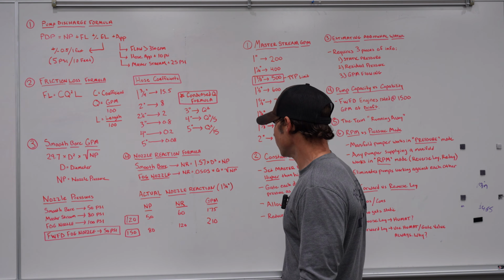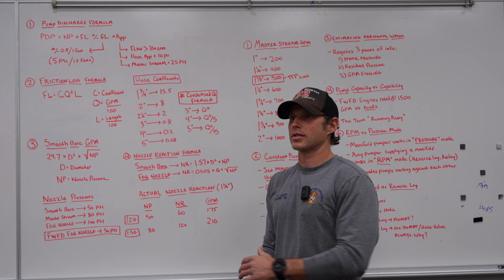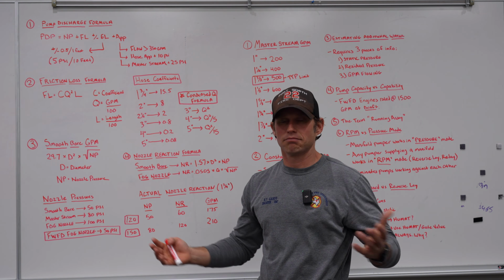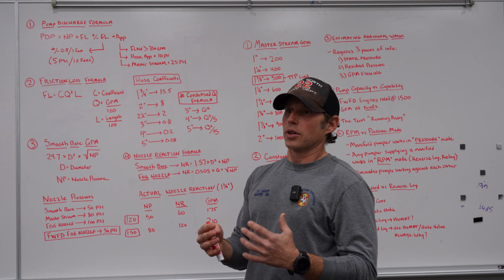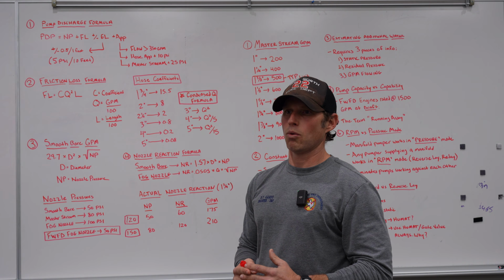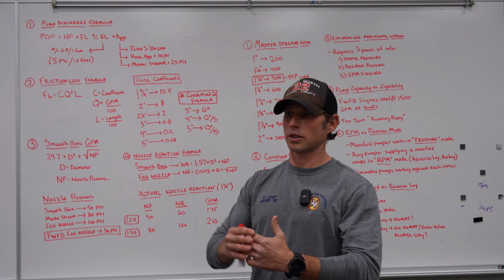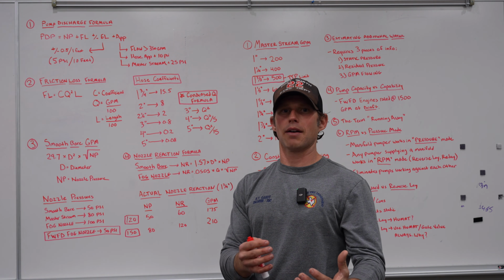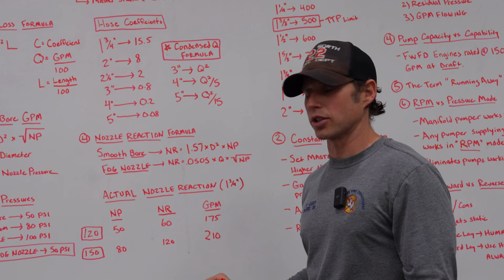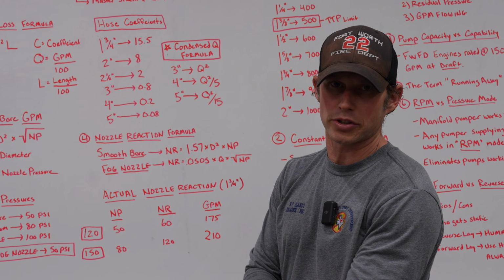So when we talk about pumping proper pressures, we have a lot of guys that say, well, who cares, just pump 150 on old hose that's supposed to be pumped 120. Okay, we've done that in the past, and it's fine. But we're going through this class in order to be better drivers, we're professionals, to be dialed in. I want my guys to go in and have fun and be as efficient as possible, and I want to provide them with the appropriate gallons per minute while they're having the most manageable hose line pressures. So some guys that put this class together initially went out and did some testing on old hose using our 1 3/4 150-foot booster sections.